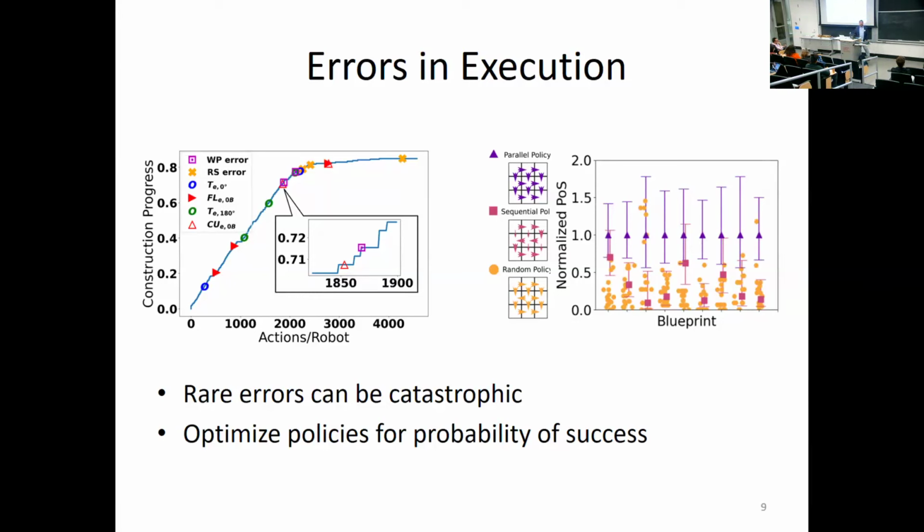Because we're able to really quickly synthesize these plans, we can now synthesize a whole bunch of plans and see whether or not a particular assembly plan is sensitive to particular errors. By error, I mean a robot moving to the left and thinking it moved to the left, and not moving to the left. You can see this particular assembly plan is actually better for local execution with a robot that has a certain error.